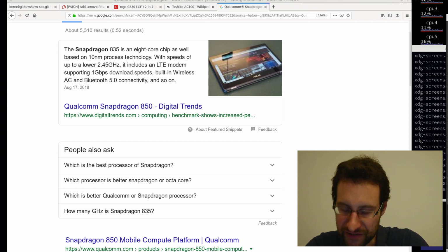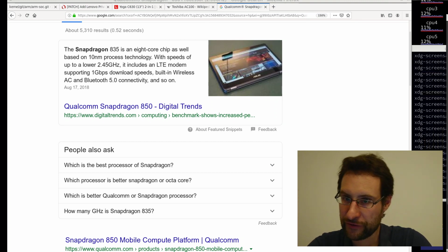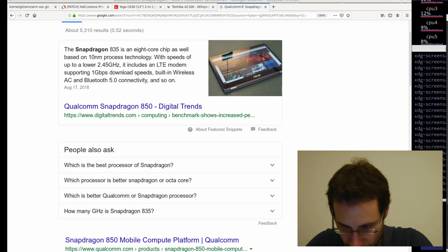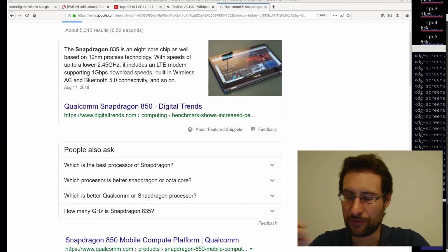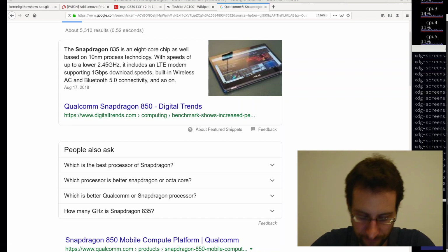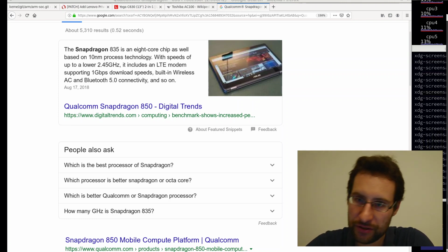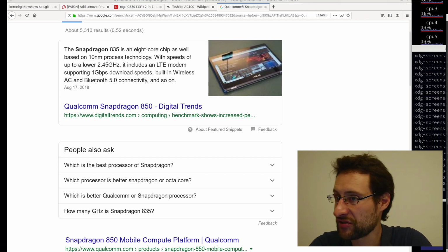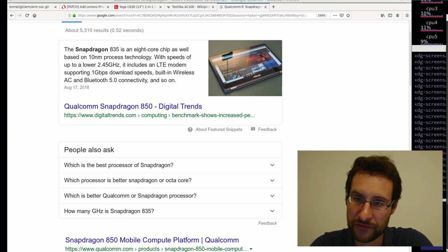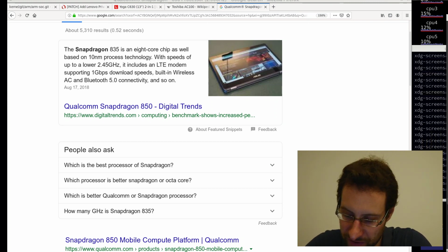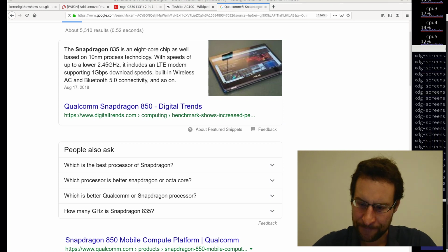I would probably at least wait for the B revision or whatever, Mark II, for having the USB ports fully working, and not have you plug something in and then it doesn't work. Basically, instead of 2 resistors, they used 1 resistor, so they saved parts, a fraction of a cent, and messed up the USB power logic. It's a little bit hilarious.